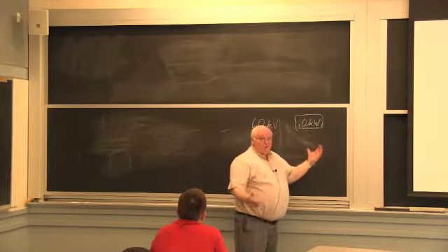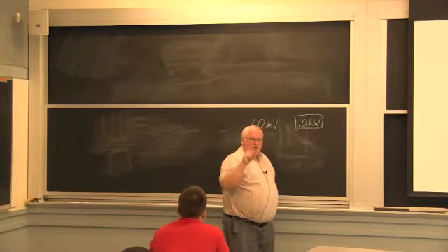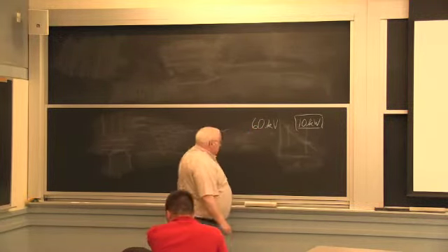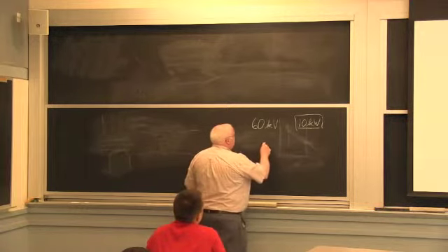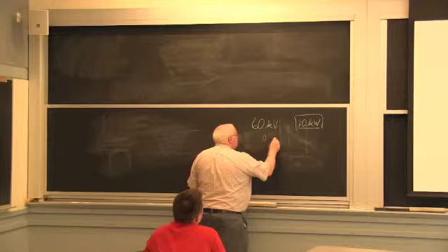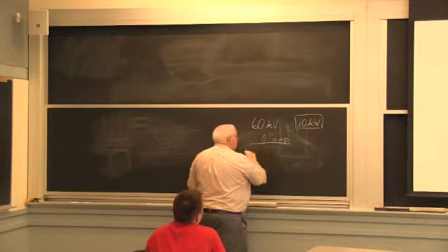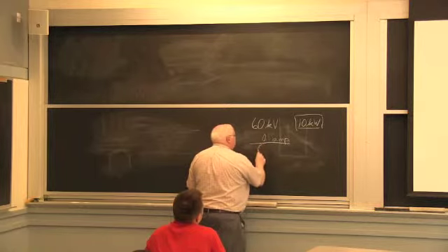I said, well, you can melt a submarine, but you don't need it. You only need 10 to 100 kilowatts for most heavy section welds. Well, it turns out you don't really want more than 1/10 of an ampere in your electron beam, and I'll explain why in a second.